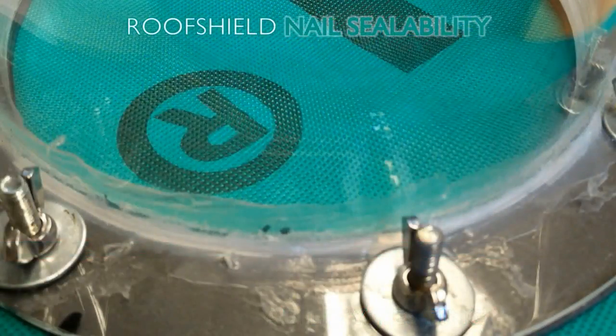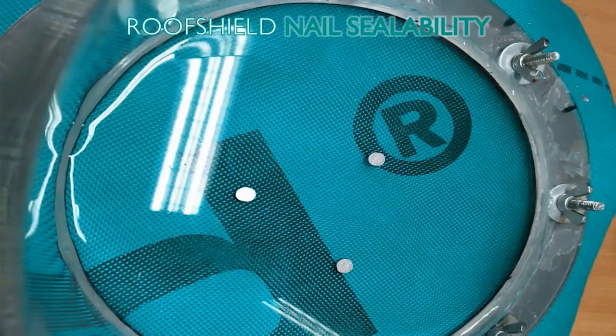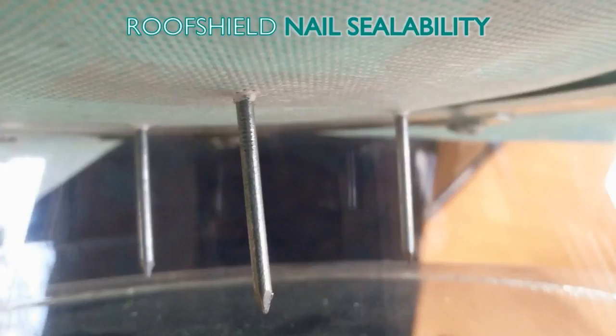In this test, a sample of roof shield membrane is mounted into a test frame, the upper chamber of which can be filled with water to introduce the hydrostatic head. The test sample is perforated with nails to simulate, for example, counterbatten fixings being made through the membrane. Once the nails are in place, the upper chamber is filled with water and the rate of water ingress or not into the lower chamber is assessed. In this case, no water is able to penetrate through the fixings into the lower chamber.